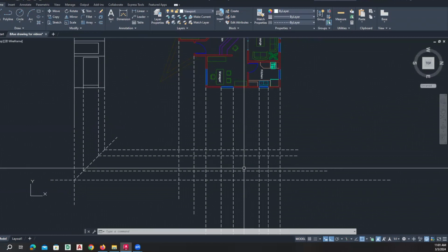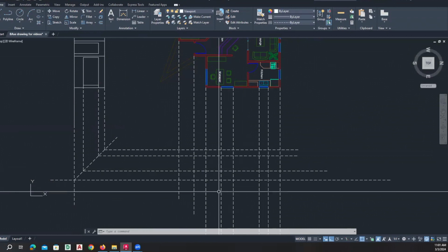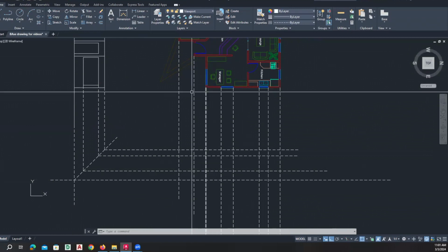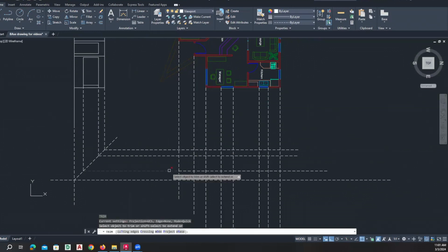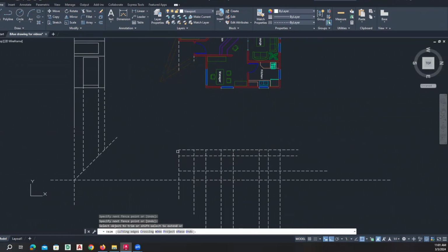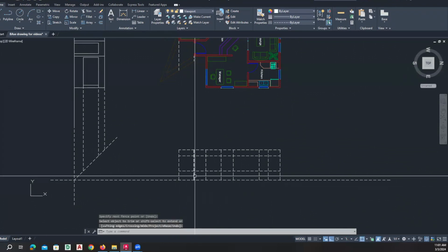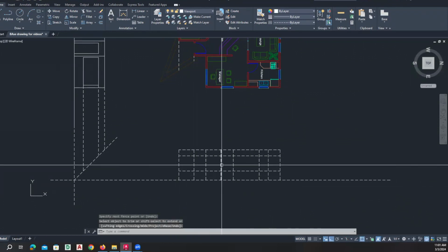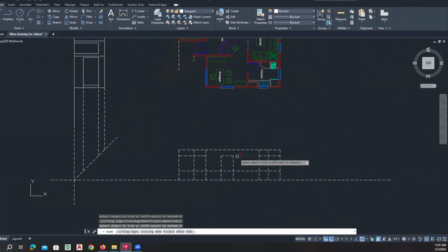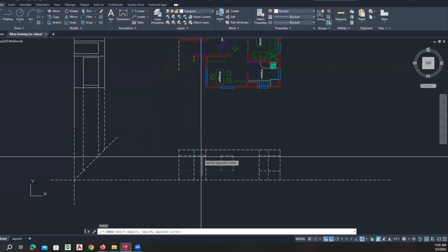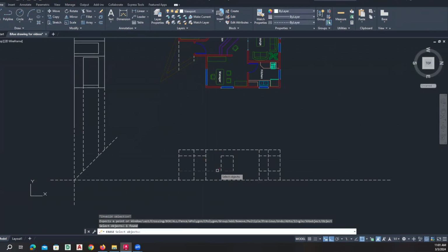And I haven't had to measure anything. I haven't had to offset any dimensions. Everything is coming from either the elevation or the plan. So I can come here and trim all of this, like that, like that, like that. And this is the first window, so this one will get trimmed. And these lines do not, oh, need to trim this one.